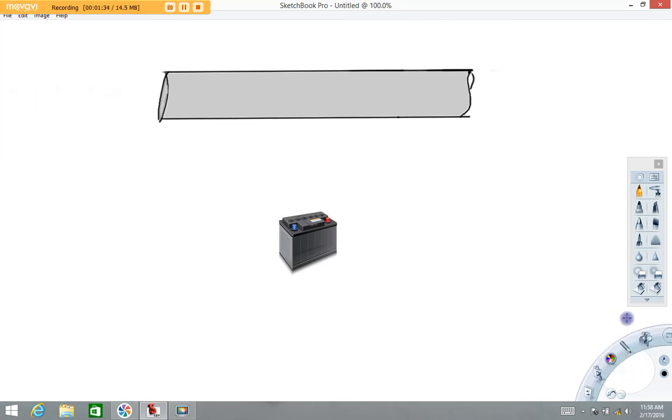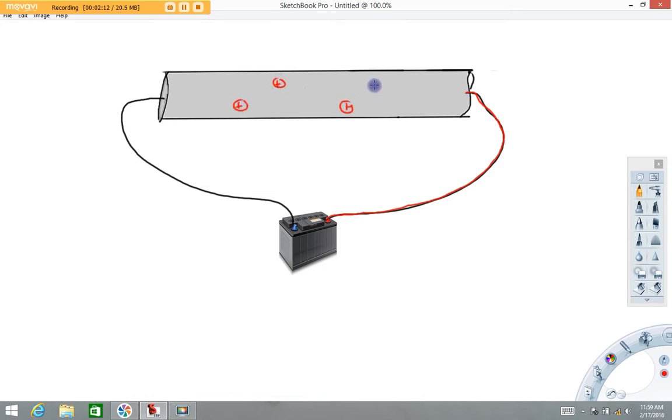So now imagine that we connect this battery, positive terminal at one end, negative terminal to the other end. Now, as I always like to do, I'm going to color code the potential. It's very important to realize that this would all be one potential. This is conducting material up to this point. This is not conducting material. Therefore, there could be electric fields in this region. In fact, there will be electric fields in this region. And therefore, my constant potential would end right there.